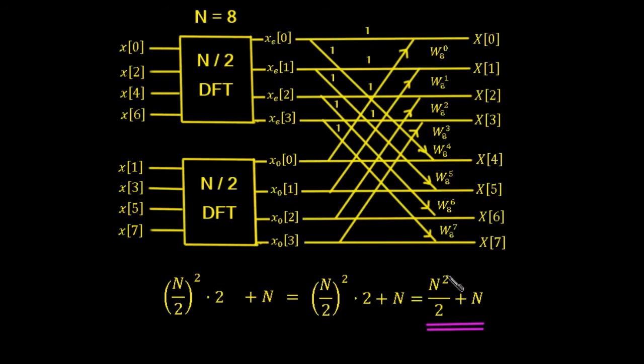So we usually represent the FFT in this type of diagram here, which is called a butterfly diagram, and you can see that it's called that because these crosses here are meant to look like the wings of a butterfly. So we take our input here, and this part of our input is only the even parts of our original 8-point DFT. So now it's going to be the values x0, 2, 4 and 6 which go into a DFT, and our odd parts 1, 3, 5 and 7 which go through another DFT.